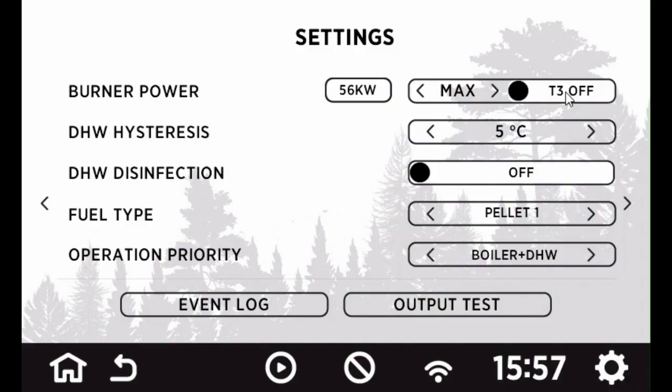You set, for example, 150 degrees of flue gas temperature, and if this value is exceeded, then the burner controller will reduce its power by 1 level. Accordingly, there are 7 levels. It will decrease once every 10 minutes, checking and comparing the current temperature with the temperature you set in the service settings, and either decrease or increase the power. This is a unique feature. It allows significant savings and increases the efficiency of the system. Accordingly, your boiler will always operate in the most efficient mode.